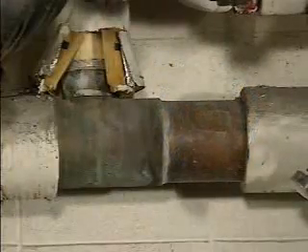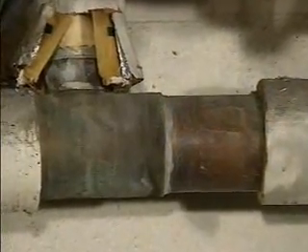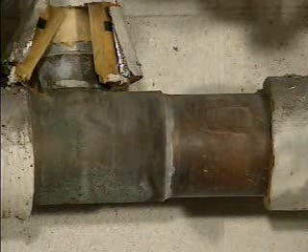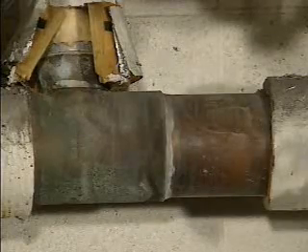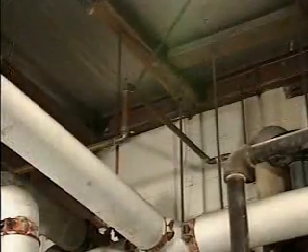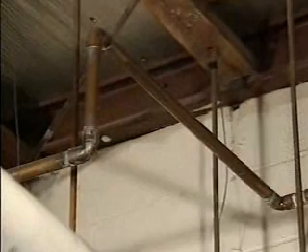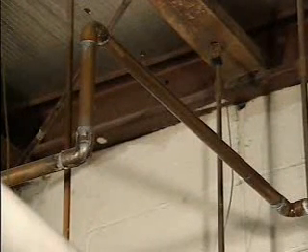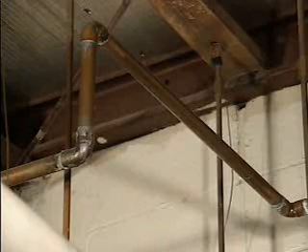Though it works well in most environments and is strong enough to handle loads that might rupture a plastic pipe, copper pipe is best suited for use in systems in which temperature and pressures are not extreme. Copper is lighter and easier to install than stainless steel. However, it expands more than other materials, which can cause pipes to split and eventually burst. For this reason, it is not suitable for systems that handle extremely corrosive substances.